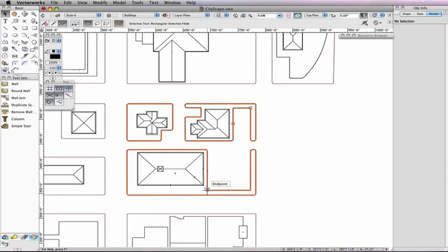You can also manually release a smart point by holding your cursor over the desired smart point for a set number of seconds, or by pressing the T key again. You will see that the small box around the object's snap point disappears once the smart point is released.